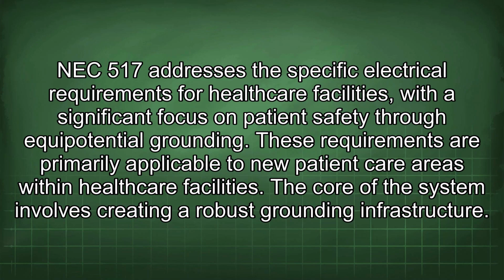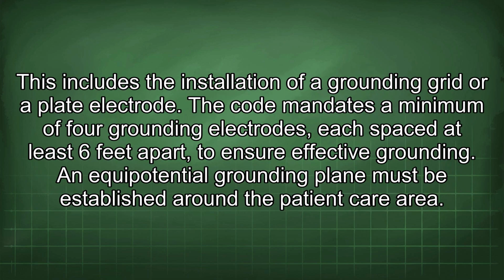NEC 517 addresses the specific electrical requirements for healthcare facilities, with a significant focus on patient safety through equipotential grounding. These requirements are primarily applicable to new patient care areas within healthcare facilities. The core of the system involves creating a robust grounding infrastructure. This includes the installation of a grounding grid or a plate electrode.